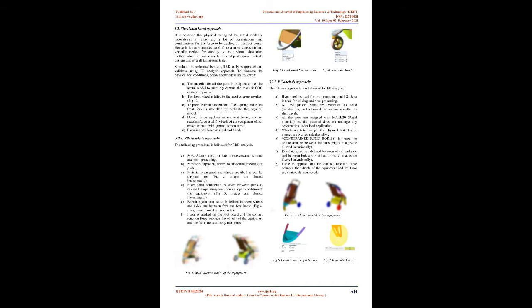Force of 40 lbf, 178 N, is applied vertically downward on the footboard using a probe. If the equipment does not tip over for the applied load of 40 lbf, then the equipment is considered to be safe and stable. If the probe slides off at a particular spot on the footboard, it is considered a pass at that particular spot on the equipment.